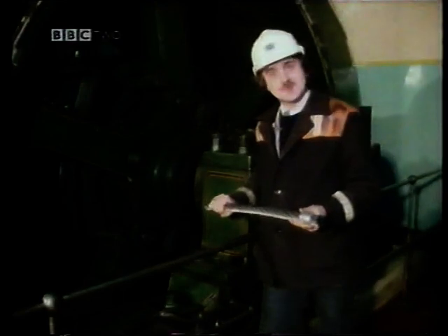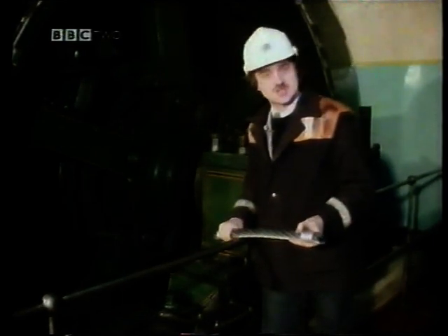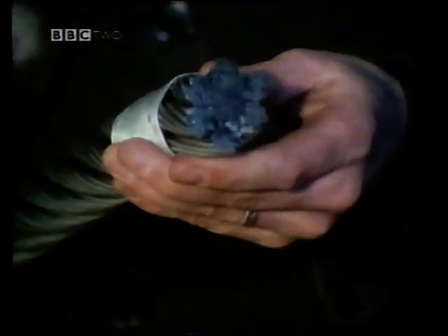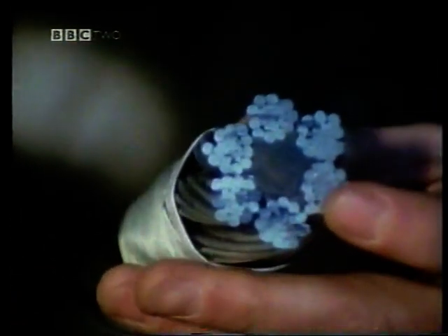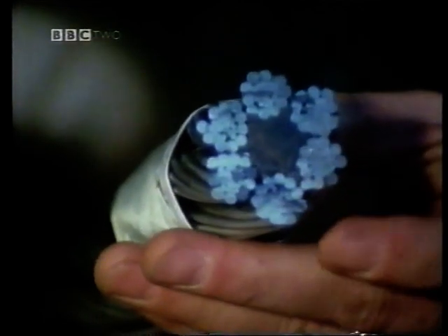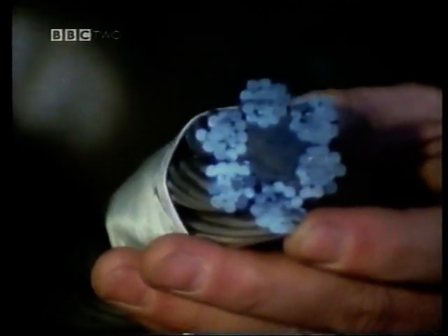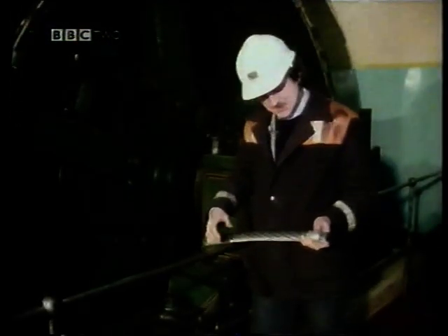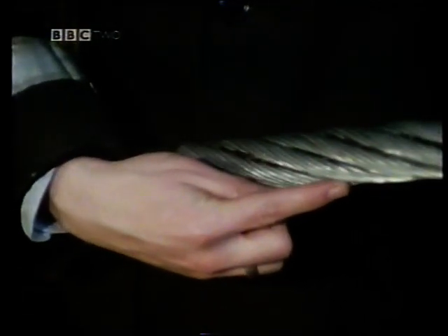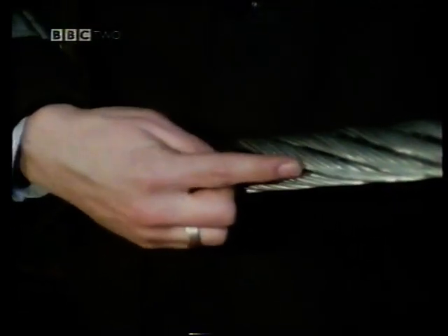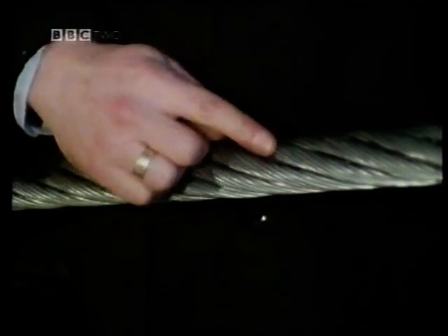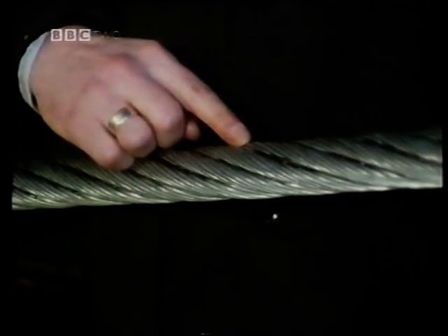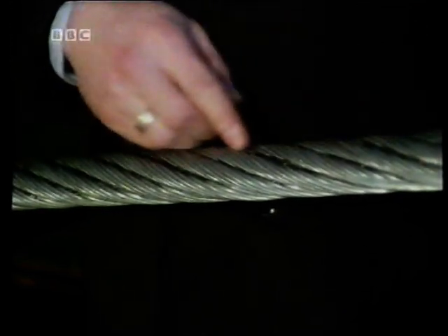Well, the rope itself has a number of features which increase its capabilities. If we look at a section, we'll see that it's made up of a number of thin steel strands, which means that it's more flexible in bending than an equivalent solid steel rope. Also, the strands themselves are twisted around the rope so that as the rope winds onto the drum, any part of a strand will be first on the bottom, close to the drum where it will be in compression, and then on the top, away from the drum, where it will be in tension, thus evening out the stresses on any single strand.